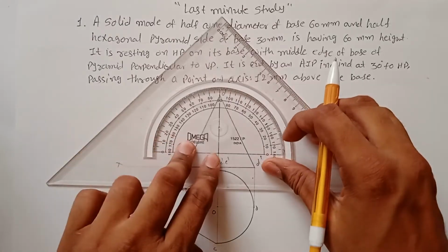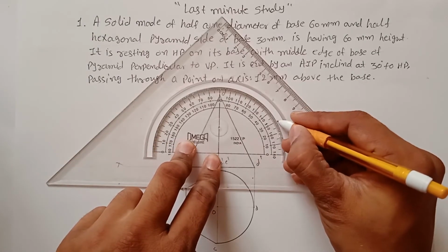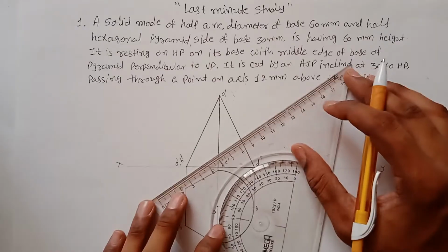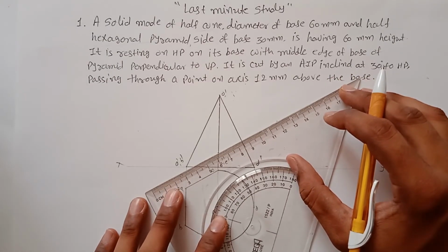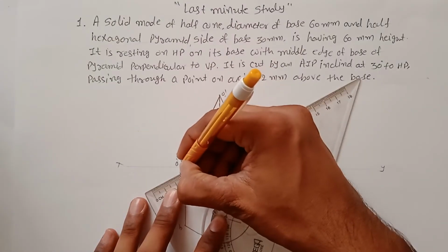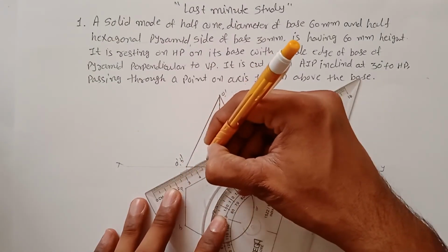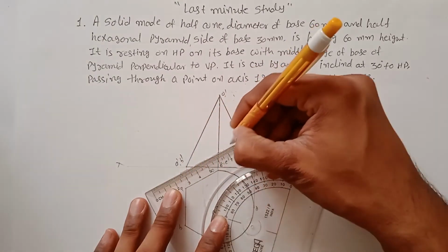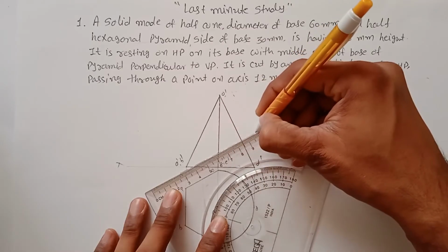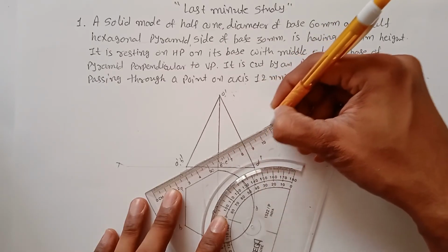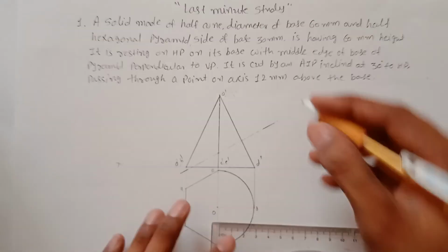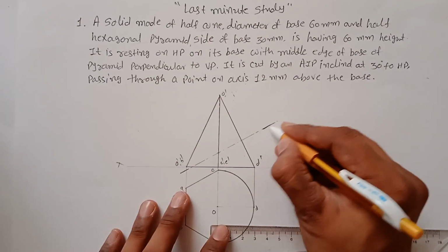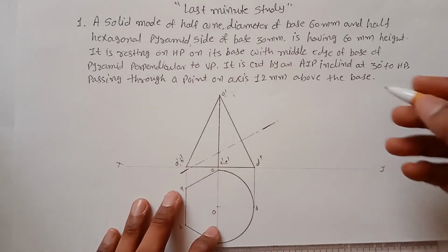This is the 30 degree angle. So the cutting plane line should be drawn like this. I will show you. Long, short, it's like a center line, but at the end you have to make it a thick line. So the end points are thick.